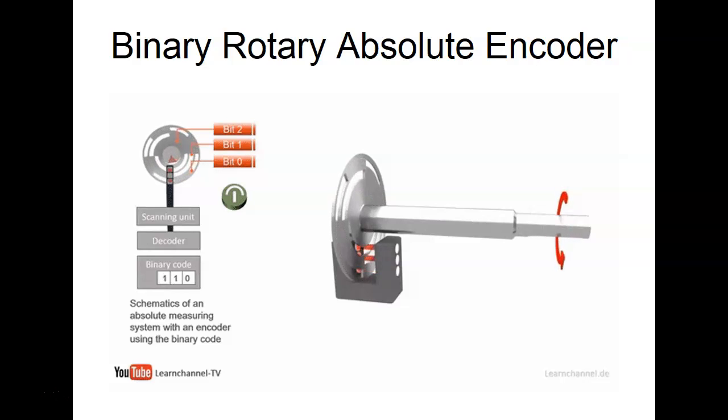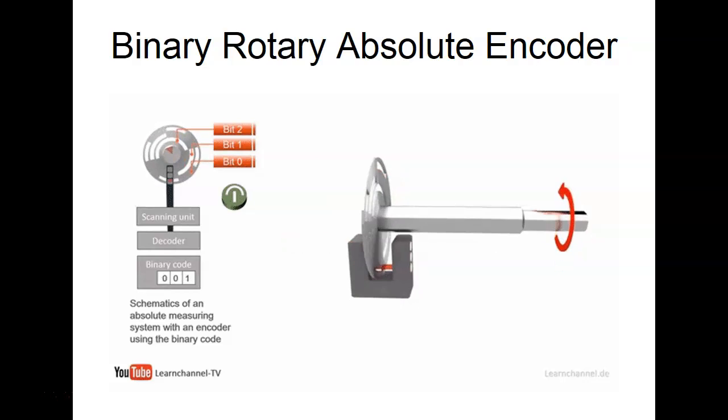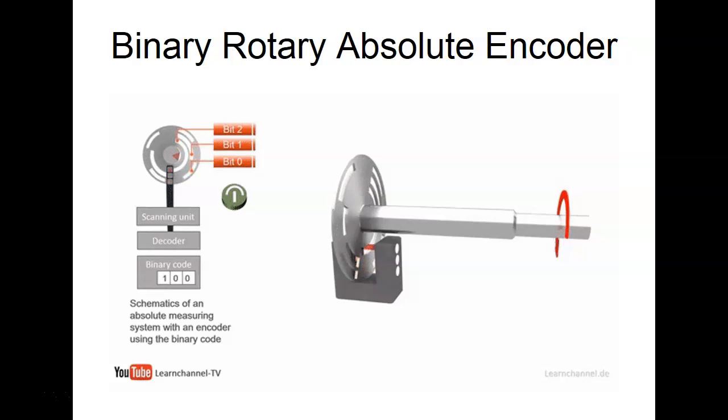Whatever we want to measure the position of, we just position this. And then as it goes across, it gives us a count indicating the location. Then we would have to interpret the count to be a certain position. So this is only a 3-band. 3-band would be 2 to the 3rd, which is 8, minus 1 would give us a count from 0 to 7.